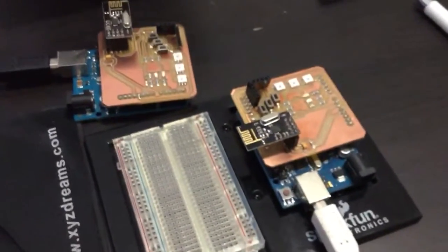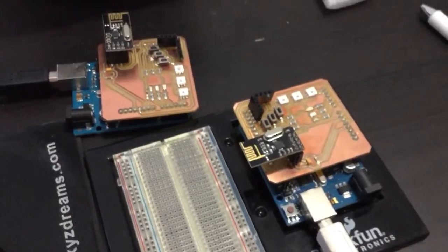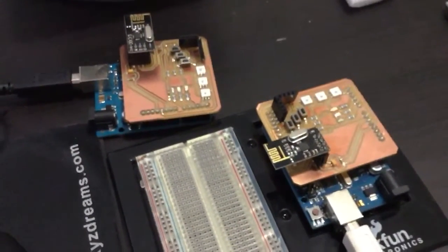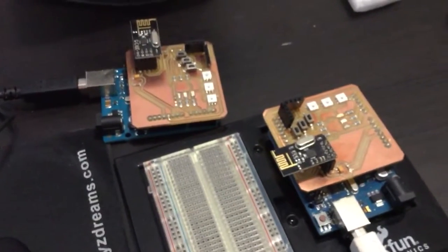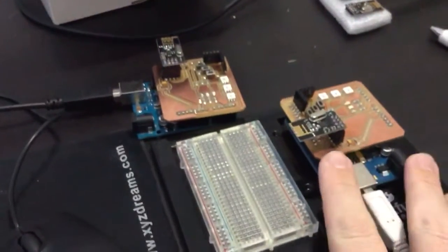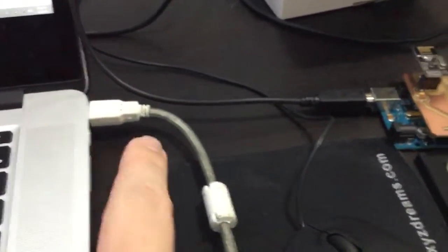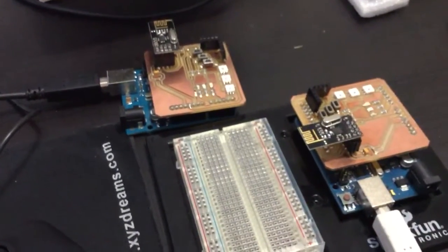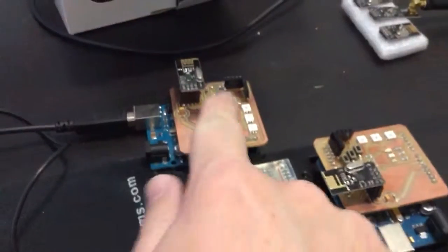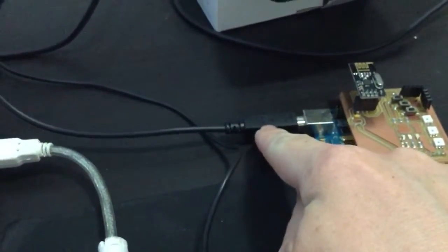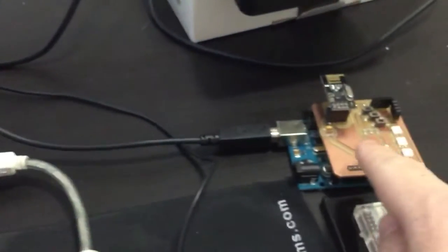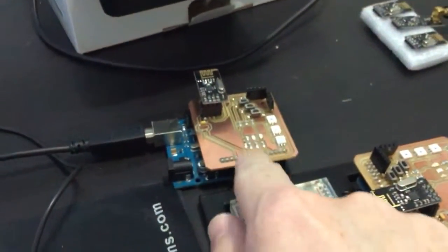In this demonstration, we have a server that's running on the left side, and a web browser on the right side, with 3 different input dials for red, green, and blue. Then we have 2 devices here that are set up as beacons. Right now they're set to listening, and when they change, they'll transmit their information as a beacon, and the other one will listen to it. The one on the right is connected to my computer through a serial port, sort of simulating a bridge through Ethernet, through the internet, to the server. This one is connected to a USB cable, but this cable is only for power. It's not connected to this computer, so this one is all by itself.